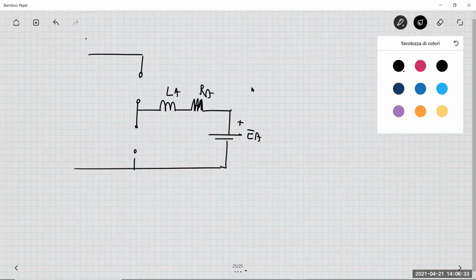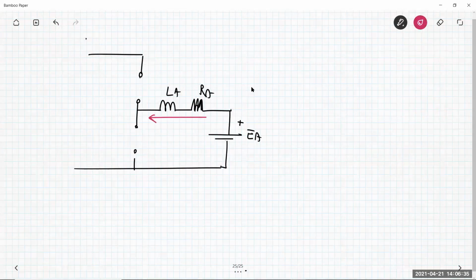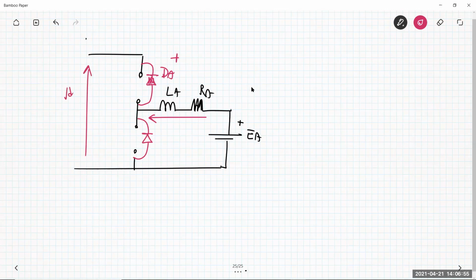The current is negative means that the current is entering here. Remember that the IGBTs are off, but the diodes are still present there. And so the only device that can conduct the current is DA+. So DA+ can conduct the current, and so DA+ makes the voltage VAN that you have here equal to VD.